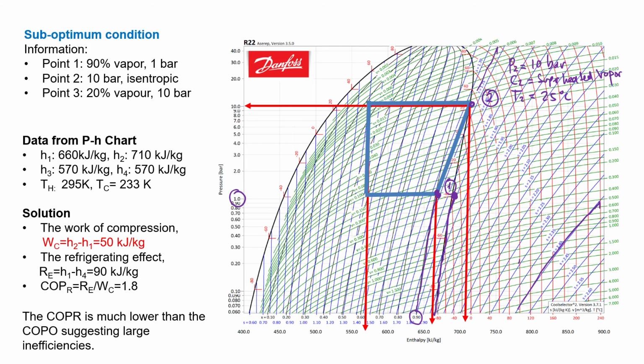So then it goes to the condensation. Normally, if we do optimum condensation, it will go to this point. Yeah, so this is the optimum. So this is a 0.3 optimum. But we have a sub-optimum. It's only condensed 80%, so 80% vapor, 20% liquid. This is the line of 10% liquid. So this is the line of 20% liquid. So we have around here. So this is 0.3. If you ask the detail of 0.3, you have a P3 equal to 10 bar.